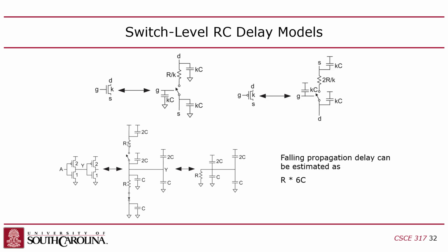These numbers are the sizes next to the transistors, right? You guys with me? Okay, so now I've got an inverter driving another inverter. And remember, we're talking about propagation delay. So we want to know how long it takes to propagate through this first inverter to get to the second inverter, right? So how do we measure that? Well, pretty much just add up all the capacitance and resistance, essentially. Pretty brain dead, right? You just say, how much capacitance do I have and how much resistance do I have? And you add it all up.